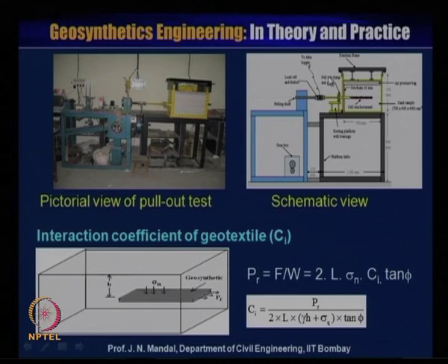This air pump is connected with the rubber, and then you are applying the load, because if we provide a kind of air bag, then the load will be distributed uniformly. So that is why it is very important that you should provide a proper air bag on the top of this soil.